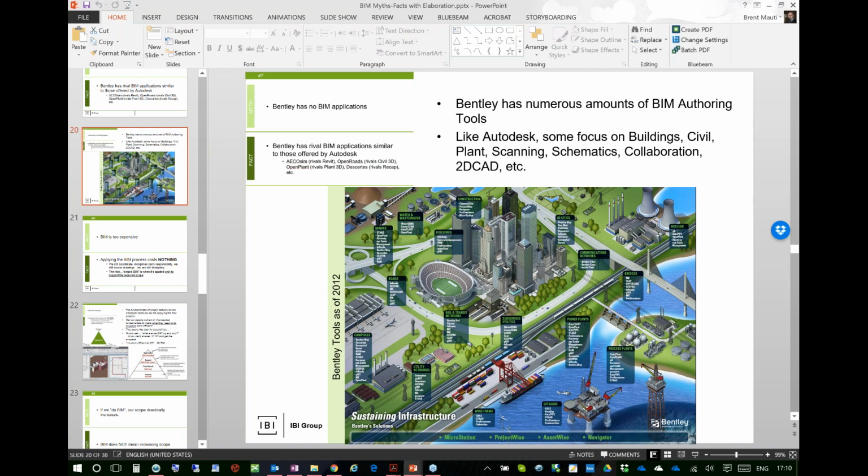Then the other benefit that DGN has over Revit or AutoCAD is when I link something or do an XREF or whatever the reference together, the data flows through. So in Revit, when you link a Revit model, you get kind of like the blob, or you link a CAD file, it's a movable blob. In Bentley, if I link structural into architectural, I can actually make cuts in my architectural based on linked elements from structural, and I can do full data reporting.